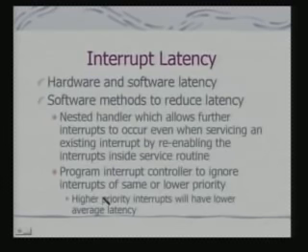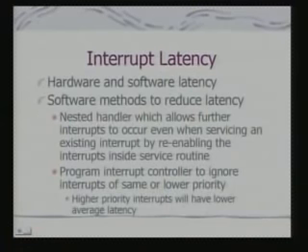Obviously, now the question is interrupt latency. I had already discussed this point earlier, and I am coming back to it because interrupt latency is a very key issue in designing an embedded system. It has both hardware and software components. Hardware is as provided by the architecture, and in the ARM example, FIQ with the provision of copy registers becoming available is a hardware solution for reducing interrupt latency.